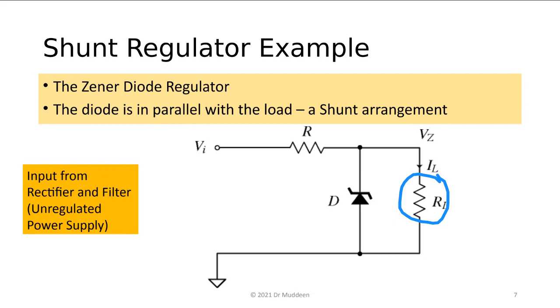What the power supply cares about is IL, the current. The power supply is designed to supply a particular amount of current, and that is what you want to make sure of. So depending on what load it is, if it's supplying certain types of equipment, IL will be specified. If you try to supply more current than the power supply was designed to supply, then the power supply is going to fail on you.